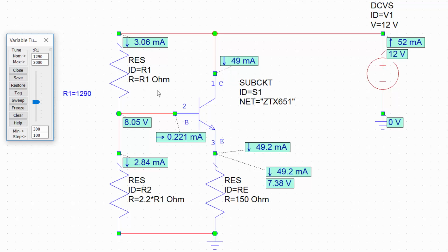So really the advantage of having a higher resistor here is simply that the power that the bias network dissipates, which would be the voltage from the power supply times the current that flows through it, will be much lower. And hence, since this power doesn't go into the signal directly, you have a much more efficient amplifier overall.